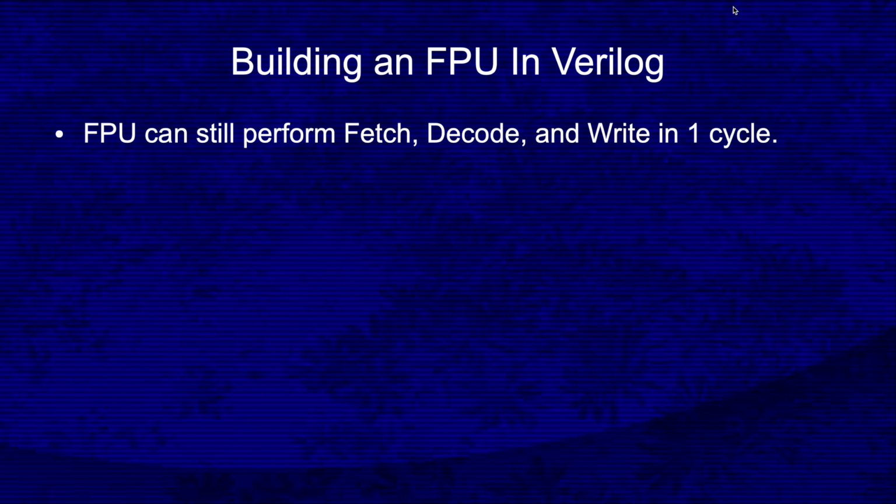In my hypothetical floating point processor, which uses 4 stages, we can still probably perform the instruction fetch, instruction decode, and writing the results in 1 clock cycle each, as we might do for integer instructions. Where floating point computations complicate things is in the execute stage. The execution of an instruction might take several clock cycles. Worse than that, some floating point instructions might need 1 or 2 cycles for the execute stage, where other instructions might need 10 or more cycles to complete.